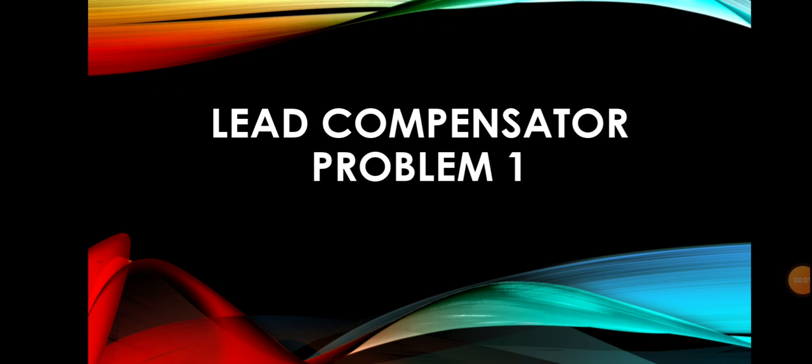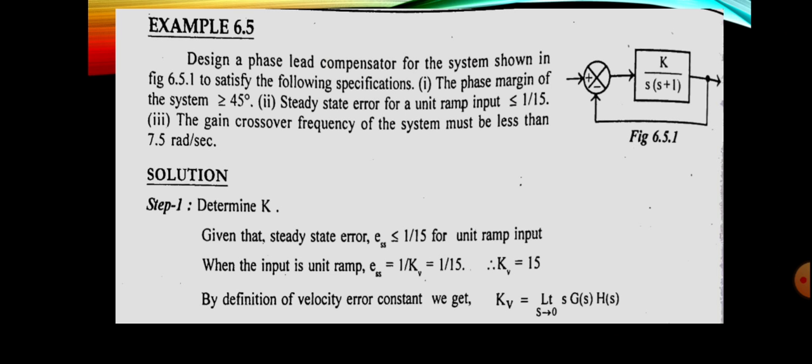Yes, students, in this session we will discuss lead compensator designing problem 1. The question is: design a phase lead compensator for the system shown in the figures, satisfying the following specifications: the phase margin of the system is greater than or equal to 45 degrees.